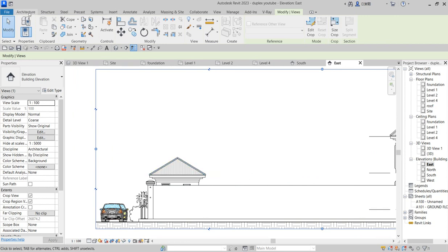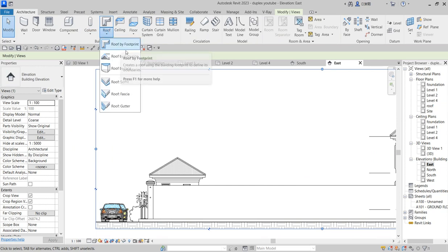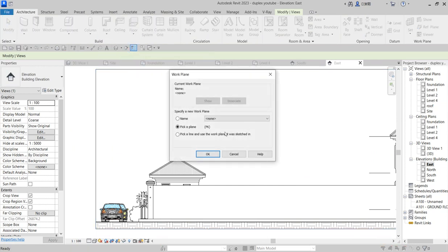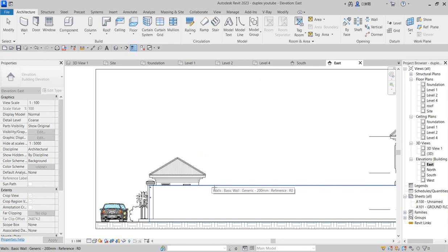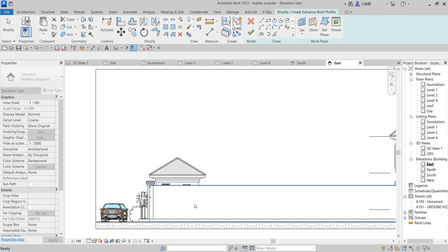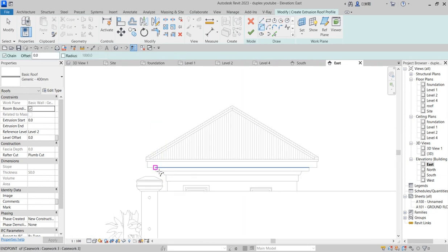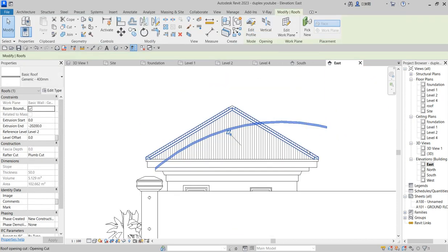space. So you click on structure and go to roof, on the roof, say roof by extrusion. Do not worry about your plane references. Click on OK and select this particular fence and say do not bother about the height, or you reduce it to something of a similar level, and you say curve, and this curve, now you take this up. You want to use the same roof material, so what you do is click finish.